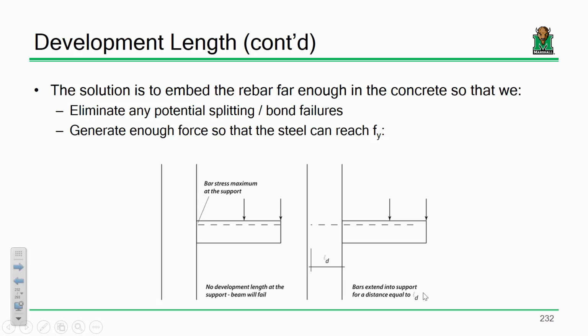See, if this is like a party deck, and people are dancing, and you have a disco ball right here, and you put the reinforcement on the bottom, that's going to be a short party, because then the concrete that's in tension has no reinforcement, and it's going to crack like crazy, right?